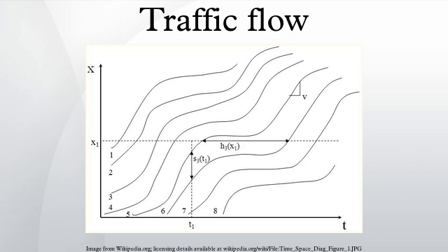In a free-flowing network, traffic flow theory refers to the traffic stream variables of speed, flow, and concentration. These relationships are mainly concerned with uninterrupted traffic flow, primarily found on freeways or expressways. Flow conditions are considered free when less than 12 vehicles per mile are on a road. Stable is sometimes described as 12–30 vehicles per mile per lane. As the density reaches the maximum flow rate and exceeds the optimum density, traffic flow becomes unstable, and even a minor incident can result in persistent stop-and-go driving conditions.